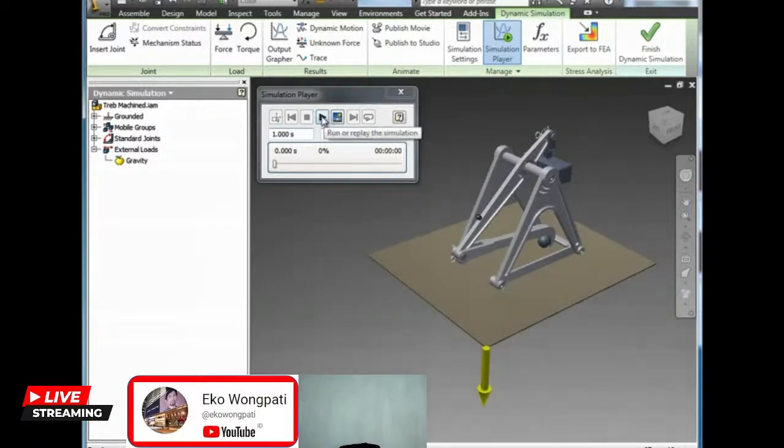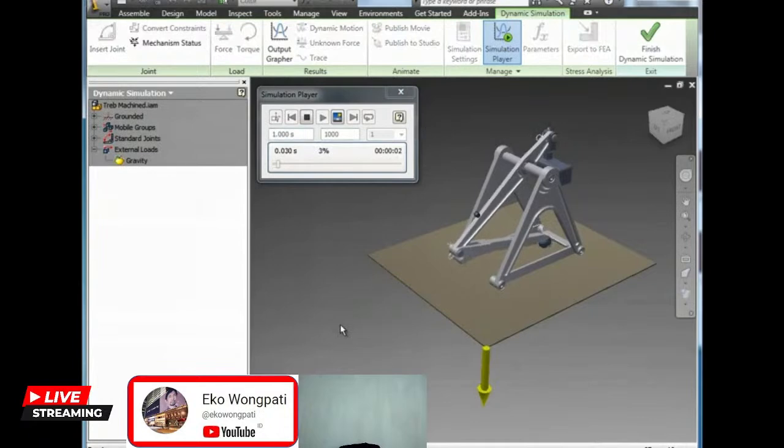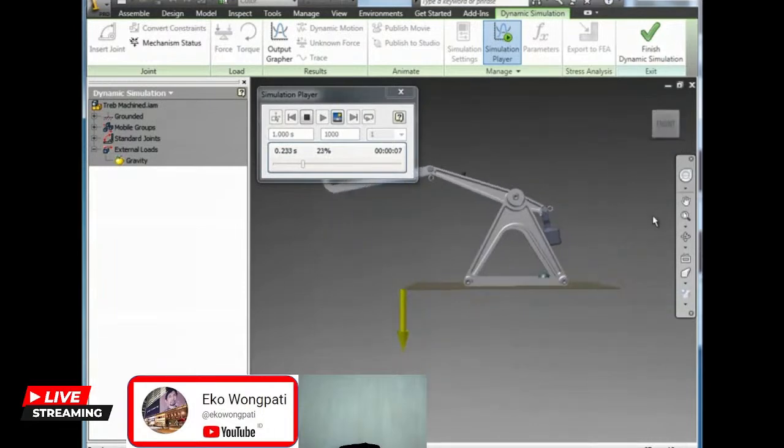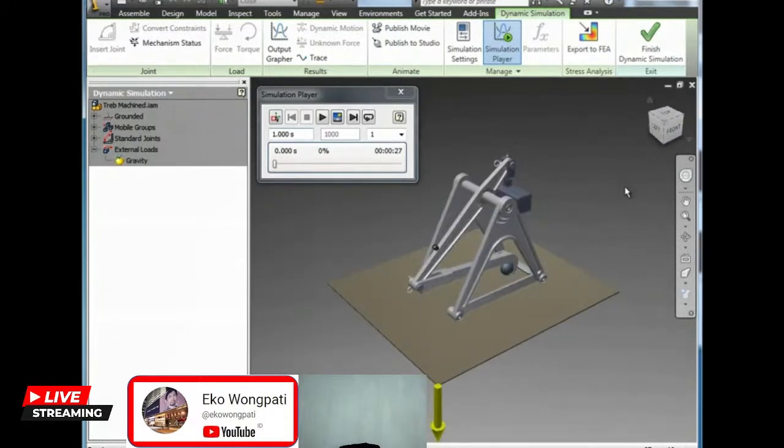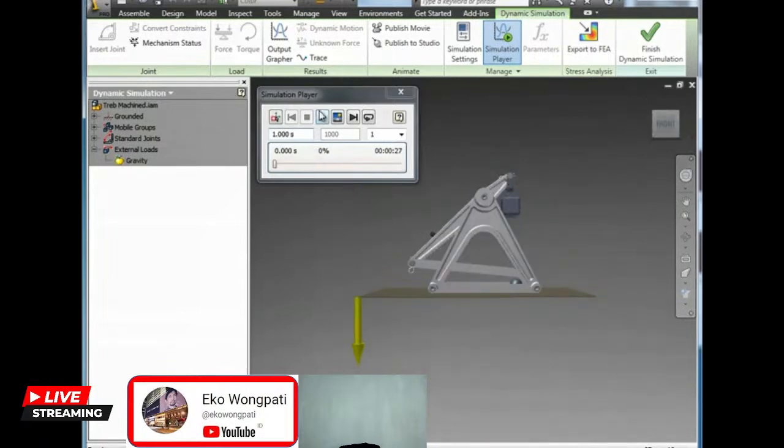And we can actually rerun this simulation. So now, if I start the simulation, you can see there is actual motion taking place in the assembly. What clicking play does is essentially release that weight that was positioned up in a higher spot and let the force of gravity on that weight be applied to the system. So here you can see it working the way I would have expected. Again, the motion is the same as we saw when we were testing it in the dynamic mode. And now we can see that with gravity everything is working.